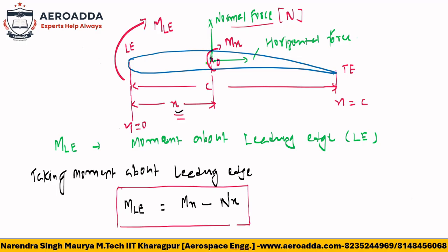Somewhere there will be the aerodynamic center. So if you see x by c or x ac by c, x is the distance along the length and c is the chord length, so x by c is a fraction of chord. X by c means the length as a fraction of chord, or per unit chord. You can see the length from the leading edge to a point with respect to chord. That is the meaning of x by c.